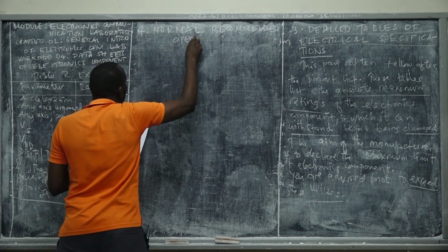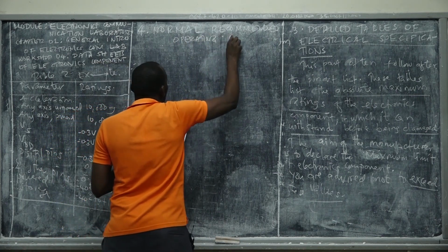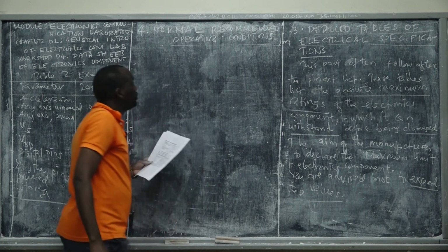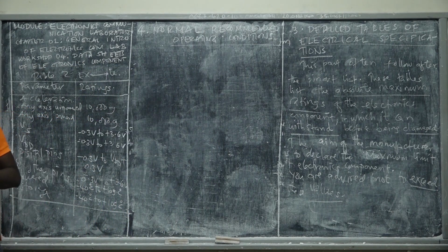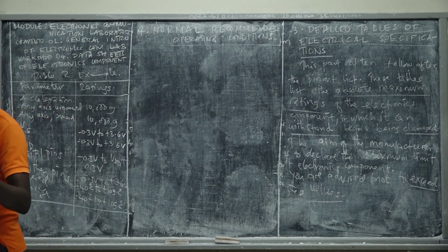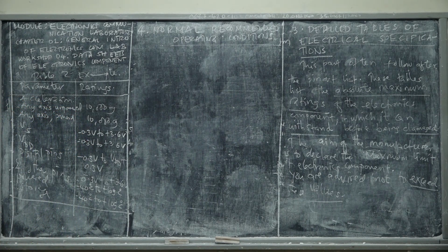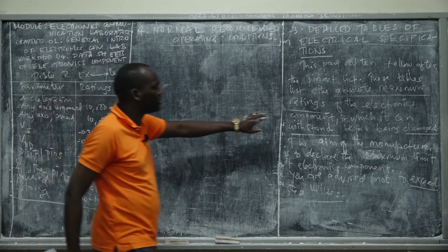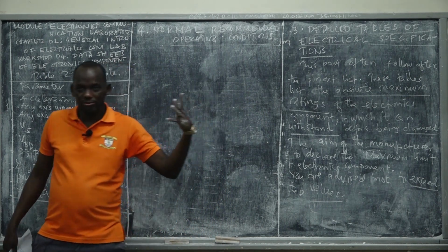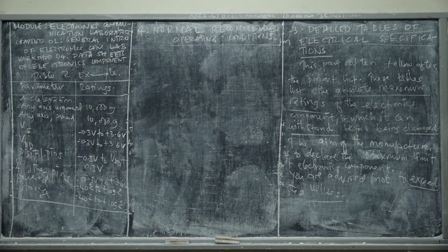The manufacturer gives the recommendation of the voltage ratings, and sometimes current ratings, that you have to maintain in order to use that electronics component without damaging it. The absolute maximum ratings give the maximum capacity of the component. Here you are being given the normal operating condition.